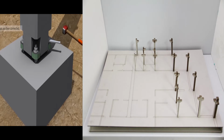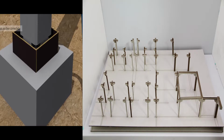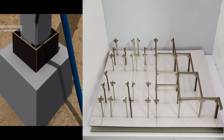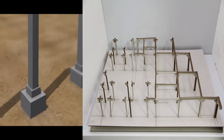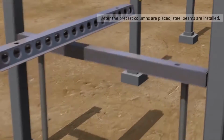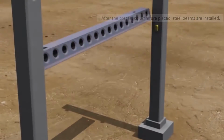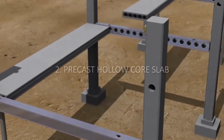After excavation and foundation, ground beams are installed. Hollow floor slab is a well-designed floor slab with high efficiency. Only half amount of the concrete is used compared to other floor slab, and it can reach the span until 12 meters. The floor slab is connected to the beam by sitting on the beam. There is no projecting reinforcement in the hollow core slab.